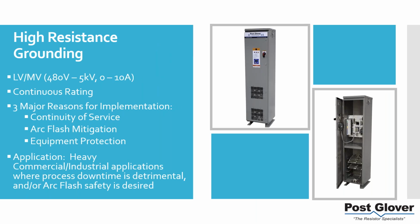Let's move on to high resistance ground. You can actually use this at low voltage and medium voltage. Historically speaking, we've been using high resistance grounding for about 50 years, roughly. Traditionally you would use low voltage high resistance ground and medium voltage low resistance ground. You would trip on medium voltage. You might have some generator protection with the high resistance ground system, but for the most part, that was kind of the rule of thumb. I would say that has changed, or at least more people are aware that you don't have to do it that way.